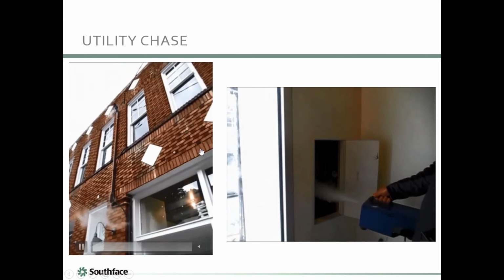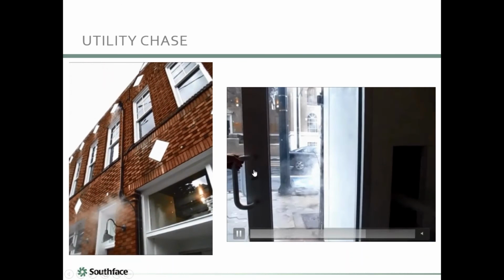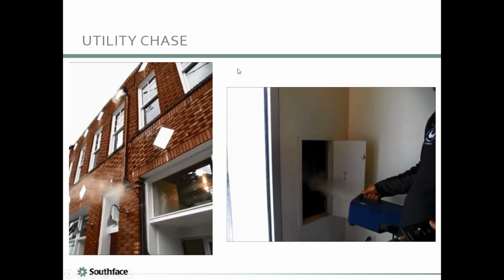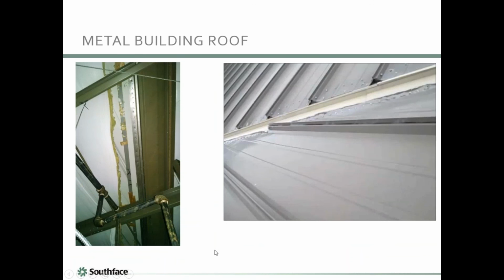It's also leaking up high at the top of the building where there's some conduit that comes out of that utility chase. So this is a real common air leak pathway where something runs from the outside of the building to the inside of the building, and where the penetration in the wall is, where the hole is hidden. It's not on the finished face of the interior. It's hidden inside this chase. So this is just a classic unsealed penetration and air leak pathway.